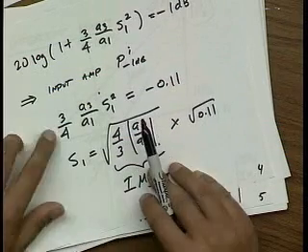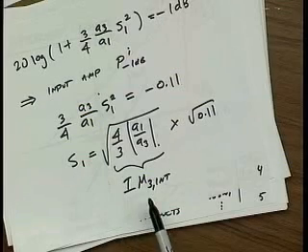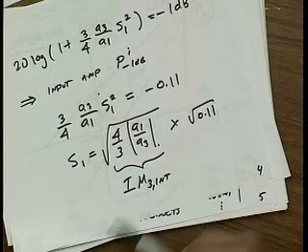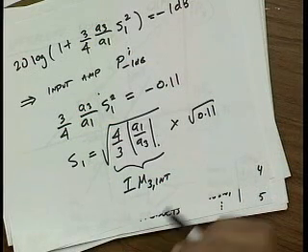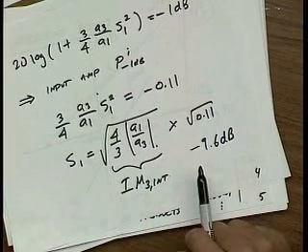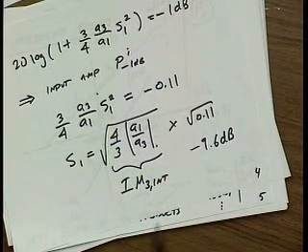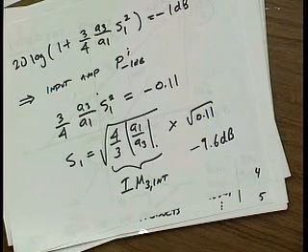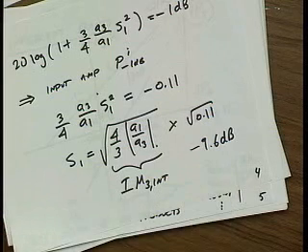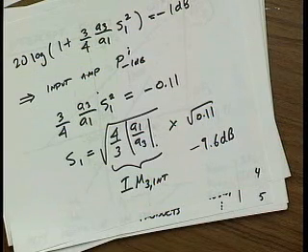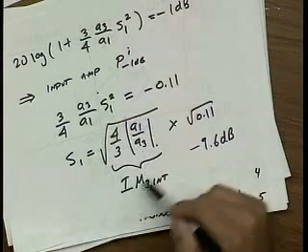And so you can see that the input 1 dB compression point is related to the intercept point by this factor of square root of 0.11. I believe that's 9.6 dB. So if you have a calculator, you can verify this. But this corresponds to backing off about 10 dB from the intercept point. So if someone tells you, I have an amplifier, it has a plus 0 dBm intercept point, okay? And I want to operate it at the point where the gain is dropped by 1 dB, then you know you back off 10 dB from that intercept point, and at that point the gain is dropped by 1 dB. Okay? So keep this number in mind because it's going to pop up over and over again in today's lecture.